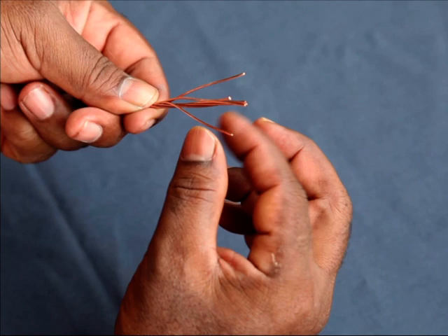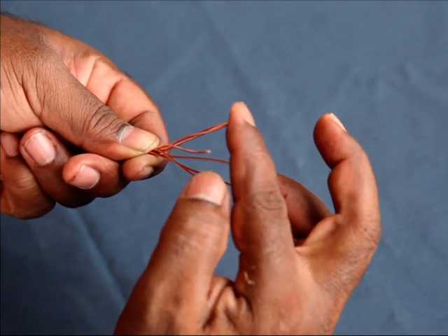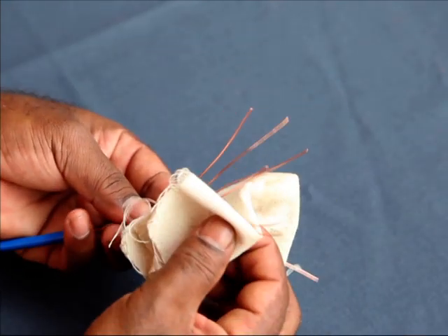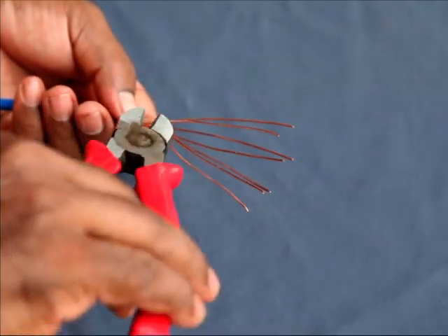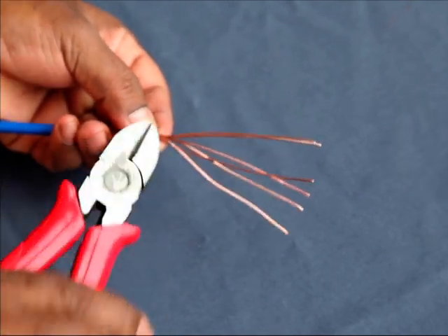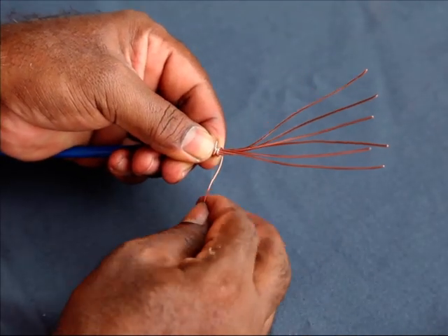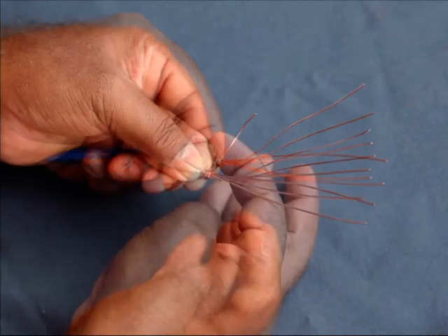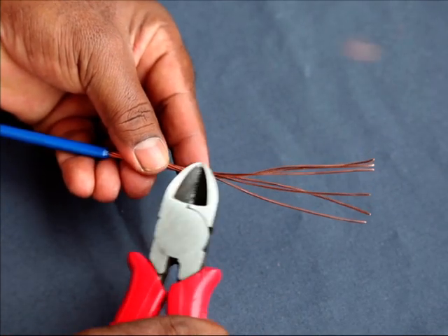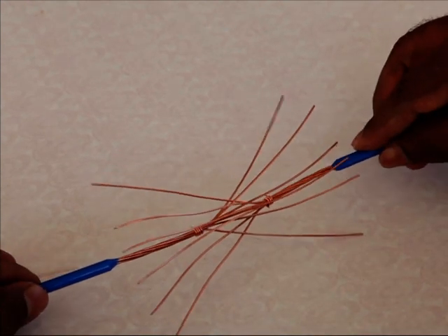4. Open the strands up to 50 millimeters from the cable insulation. Clean the strands with sandpaper and cotton cloth. 5. Cut the center strand of both cables close to the twist, about 70 millimeters from the free end. 6. Make a binding on the twisted part of both the cables. 7. Interlace the strands, keeping the center butt.